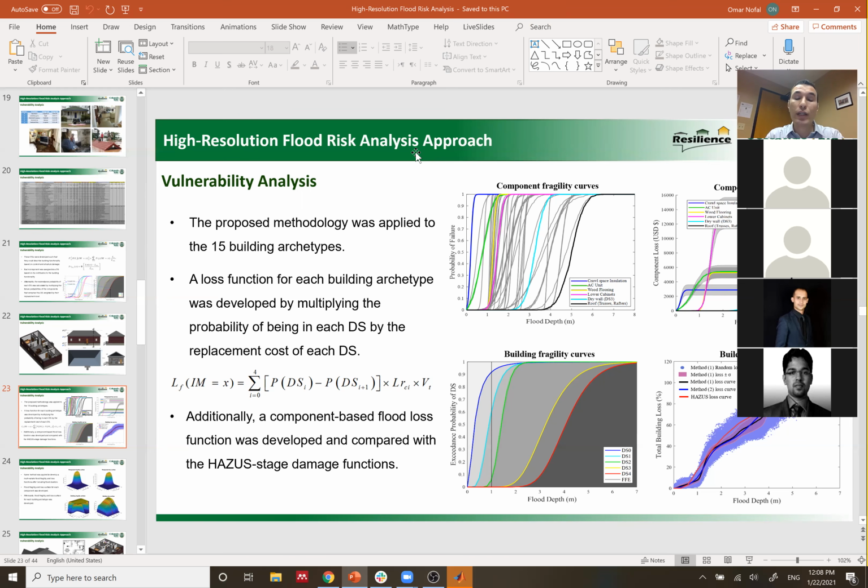That's why we need to do calibration and validation for our model. We need to have at least 1 or 2 gauges in the study area or some high water marks and validate our work to match what happens in the field. So we still need some validation and verification to verify the hazard model. But let me get to the exposure and vulnerability analysis.